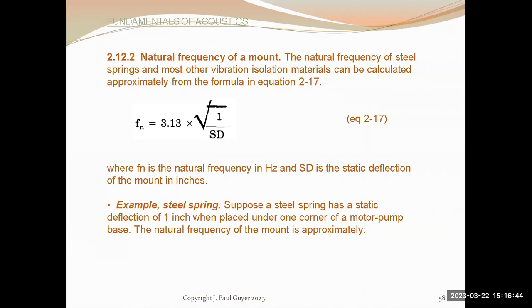In other words, in an unloaded condition, the spring isolator is 2 inches long. And then when you put the fan on top of the spring isolators, the spring isolators squash down, or there is a static deflection.